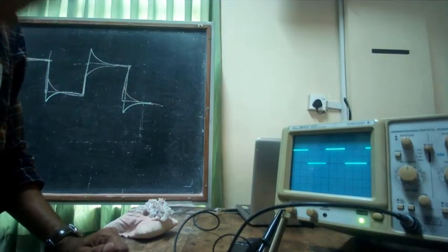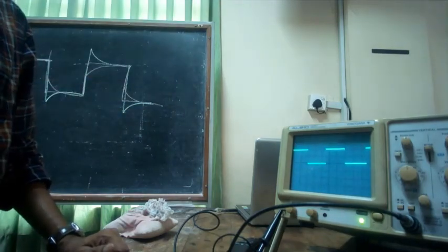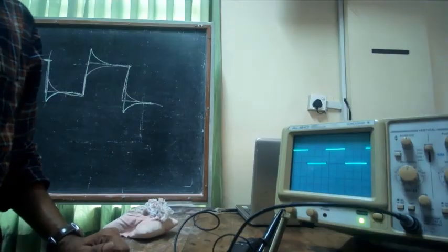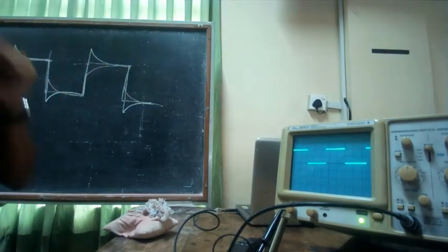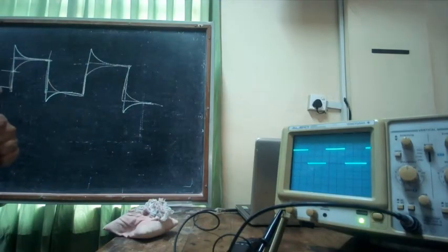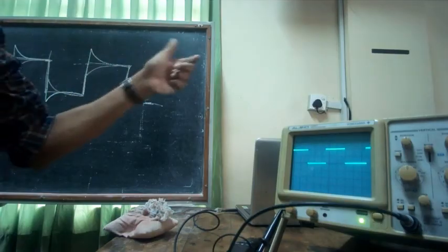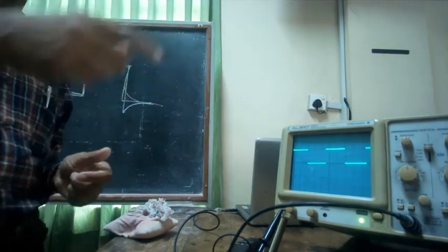But to get the exact value, you need to know its value has to be that, because otherwise you may have a variable attenuation depending on the resistor value and the capacitor. So you have to have a tuned probe to make measurements. This is called probe tuning. It applies when you have large signals or high frequency signals or multiple frequencies. These square waves have multiple frequencies.